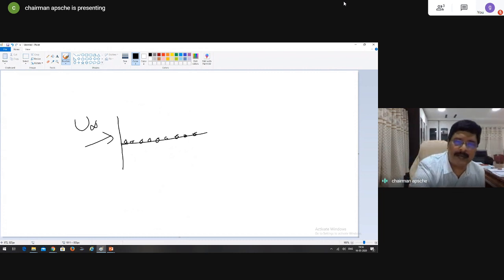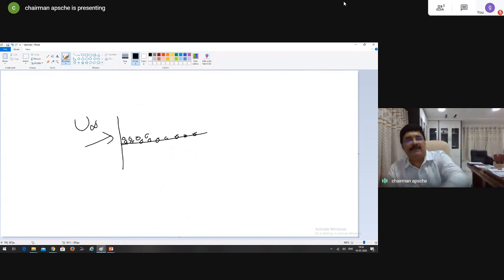Now, what happened? Let me analyze it layer by layer. One layer of molecules settled down on the wall because of the wall friction that is encountered. Now, the second layer of molecules are not coming in direct contact with the solid plate, because one layer of molecules has already settled down, and by the no slip condition they are not moving, they are stagnant.